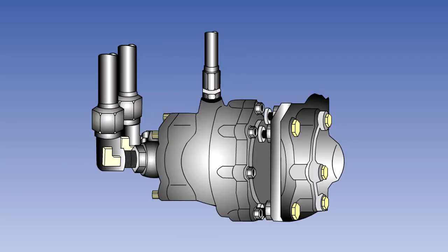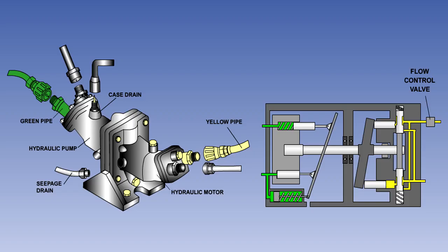Hydraulic motors are a form of rotary actuator, and are sometimes connected through gearing to operate screw jacks on such components as trailing edge flap drives. Illustrated here is the B747 trailing edge flap drive motor. It is mounted directly onto a gearbox, which in turn transmits the drive to the flaps through a torque tube. Hydraulic motors can also be used to drive generators or pumps. In some aircraft, they are used for driving a hydraulic pump unit, thus enabling power to be transferred from one hydraulic system to another without transferring fluid.